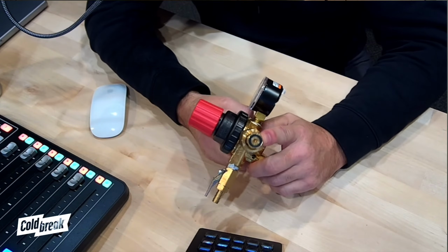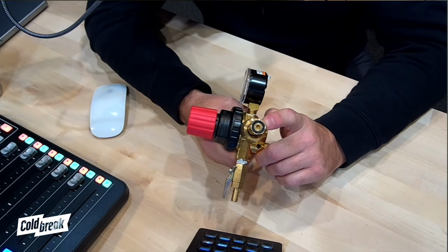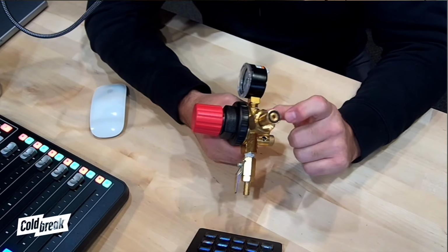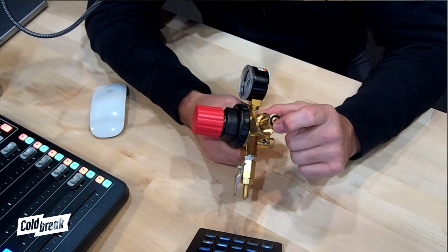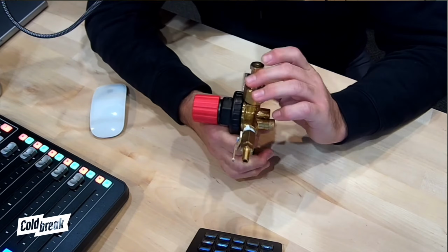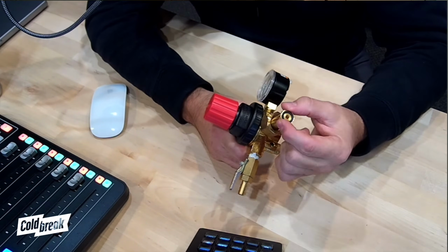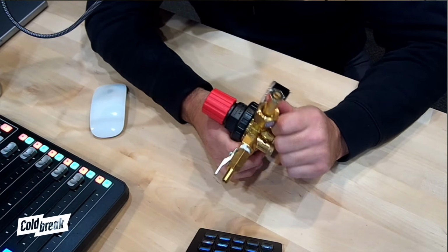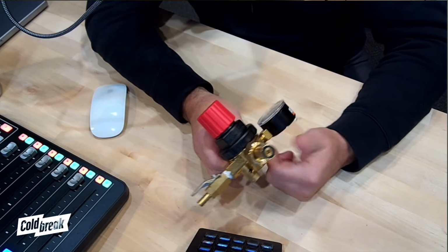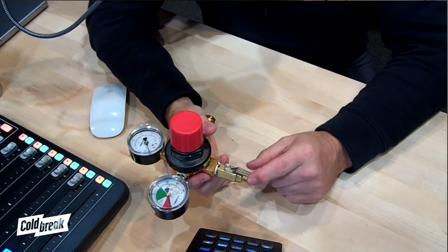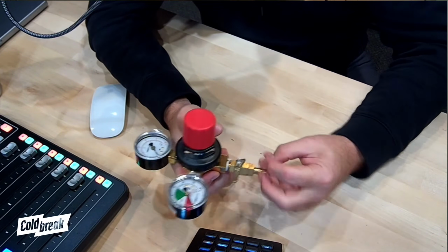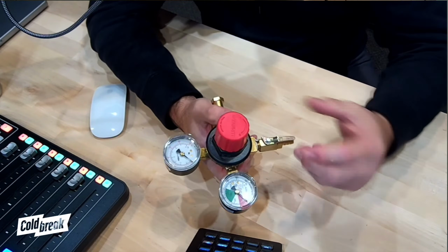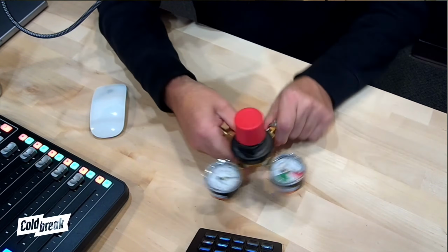Also, when you're connecting it to the CO2 tank, you never want metal on metal, right? So you always want some sort of washer between them. The tap right regulators that we sell have a built-in one. These will go bad. If they ever do, they also make nylon washers that can replace these as well. And if this ever does come out, it's kind of hard to tell, but this actually can unscrew with an Allen wrench. And then at the very bottom here, it's got a cutoff check valve on it, in case you just want to shut the gas off from here rather than at the tank or turning the gas all the way down. So that's a primary regulator.